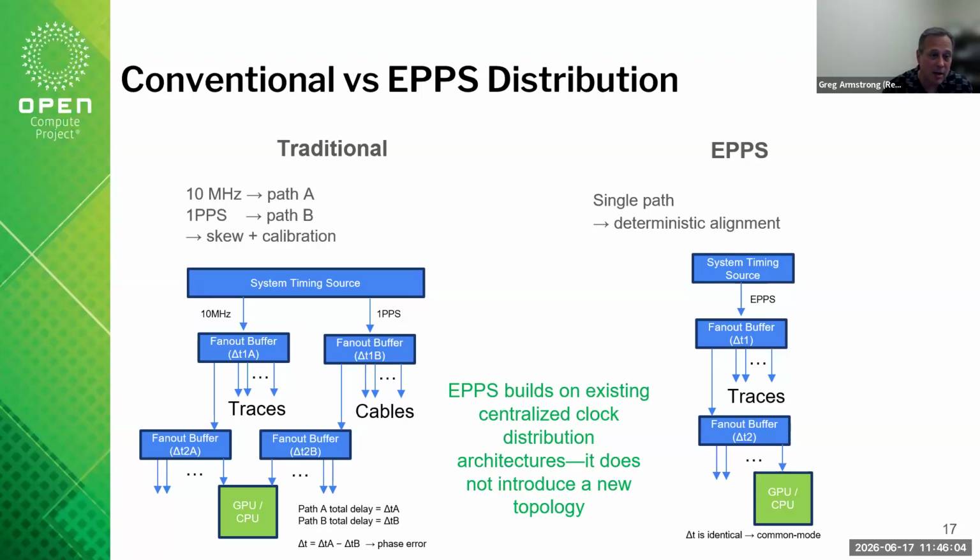But then if the time card is sending the 1 PPS, it may have to fan it out because it has to send that clock to maybe 5 cards. Well, that means you have to split the signal into 5 copies, right? And then you got to screw on all 5 of those cables to each one. That means they're different lengths, right? There could be bends, there could be things that could affect the signal that attenuates it. All this stuff can start having impact, or they didn't screw on the connector tight enough. Jason Rock highlighted some of that where he found that was one issue where he just found out it wasn't screwed in tight enough, right? So it just wasn't making the connection. And he was wondering why he couldn't detect the 1 PPS or why it was very attenuated when they were trying to look at that signal as it was recovered, right?